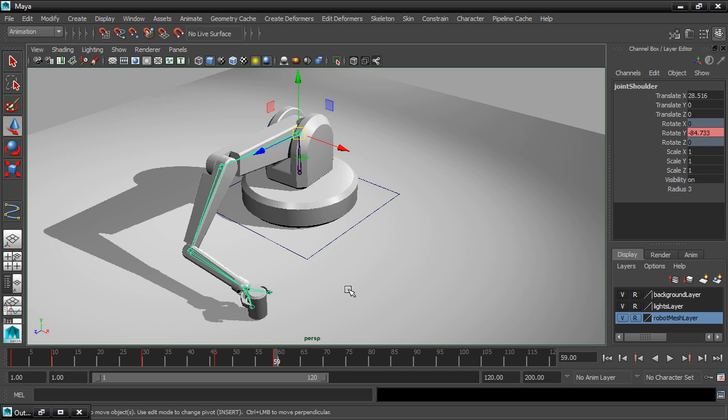If you have a standard link, it's forever. You can't break a link in the middle of an animation, nor can you create a link in the middle of an animation. A link is either there or it isn't for the entire duration of your animation. But with a parent constraint, you can have multiple targets and you can turn them on and off at different times. That's what I'll do here with the little can.